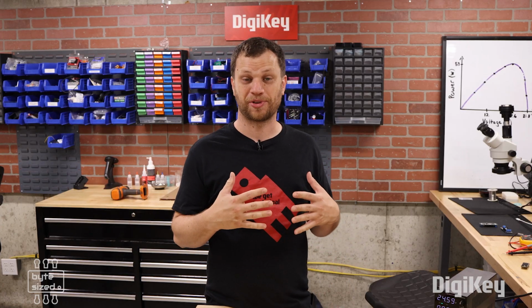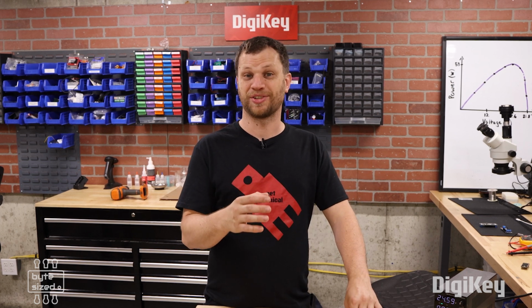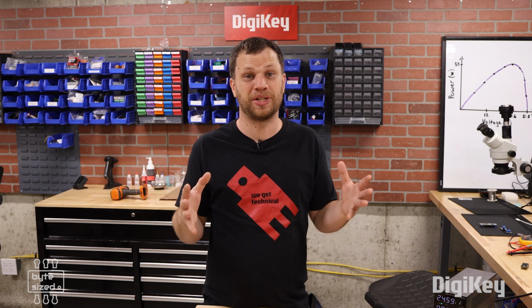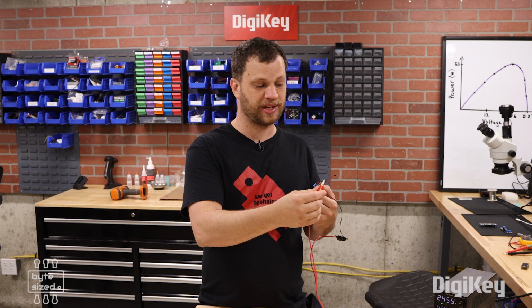Okay, after looking at my schematic for a couple minutes, I immediately realized one problem. The current limiting resistors that I had in series with those LEDs were not the right value. They were way too high, which meant the LEDs were too dim to even light up. I went ahead and swapped out those current limiting resistors, so now the LED should light up.